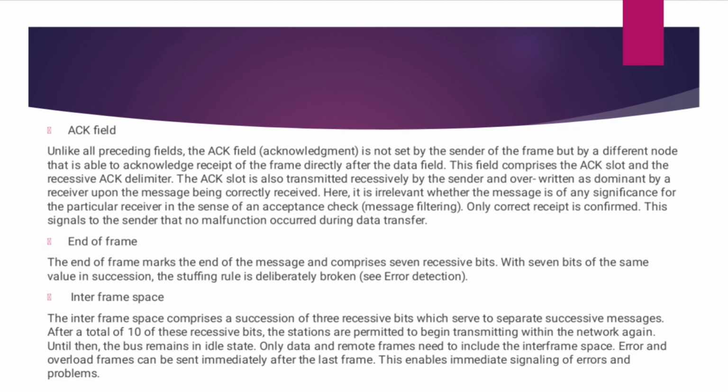End of frame. The end of the frame marks the end of the message and comprises 7 recessive bits, with the 7 bits of the same value in succession. The stuffing rule is deliberately broken.